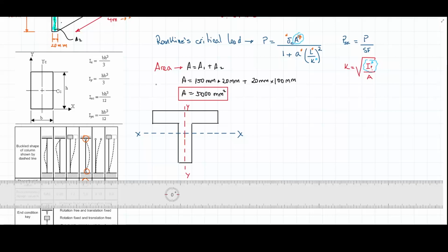All right. Then I know that to calculate the inertia of these types of sections, I could take advantage of the fact that these are two rectangular sections tied at this point, meaning that I could add both moments of inertia to obtain the total moment of inertia of this section. However, when we define moment of inertia, like in this figure that you're seeing right here, moment of inertia is defined with respect to certain axes.